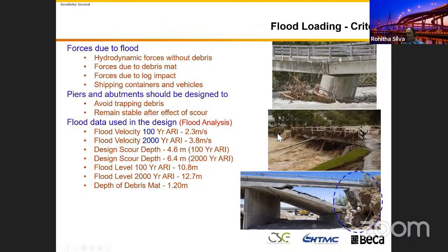They calculate the cross-sectional area of the river or creek, get the volume of water going per second, and then divide the volume rate by the area. That's how they calculate the speed sometimes, or else they can give you the value on the top surface of the flood. It depends on the modeling.